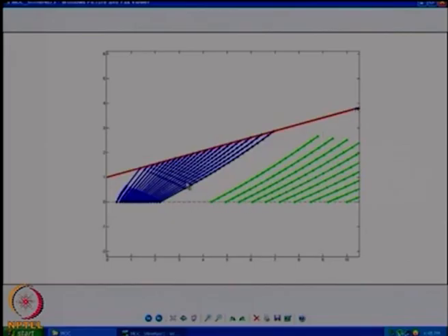And similarly, I will just take every characteristic to the axis. From there, I will just go this way, all left running characteristics. If I want to switch from right running to left running, I will have to do some patch like this. If I already had a right running characteristic pattern, I did not draw the full fabric. I just drew one set of threads of the fabric. The other set of threads will be this way, which I did not draw. I just put points there.